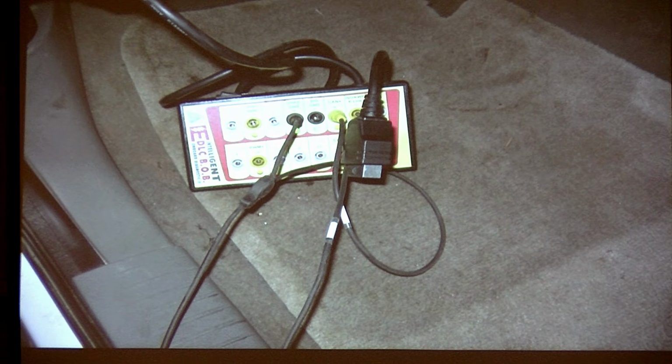The other thing that's very helpful to have is a scan tool that you know can communicate with the bus. A factory scan tool is always good if you can get it. Because then if I can't communicate, I don't second guess, oh, wow, I wonder if that scan tool can talk to that module. And you just don't know. But if I've got a factory unit or equivalent, then I know I can. So if I can't talk to it, you know that the communications to that module are down.